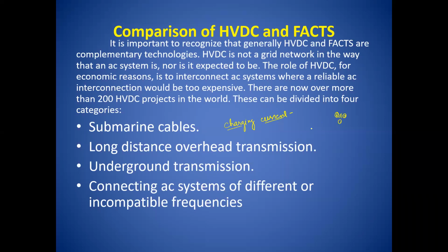I will give an example of cable capacitance. During the lockdown period, our entire campus was off, meaning the hostels had zero load. Hostel number 1, 2, 3, whatever it may be, the load on all hostels was zero. The underground cable delivers only the charging current.